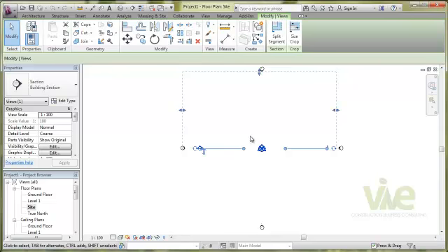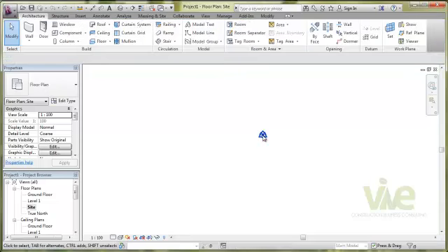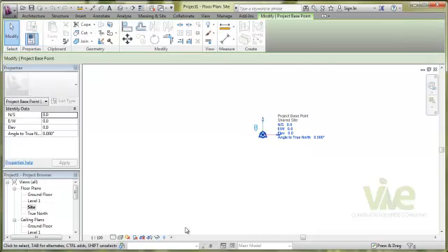We also have this little triangular circle icon at the center. When I zoom in, it keeps its same size. This represents 2 things. We have our project base point, which is a very important parameter when we're modeling in Revit. This will establish the base point for our project. We can keep it so that it matches AutoCAD plans or any other software plans that we may have.